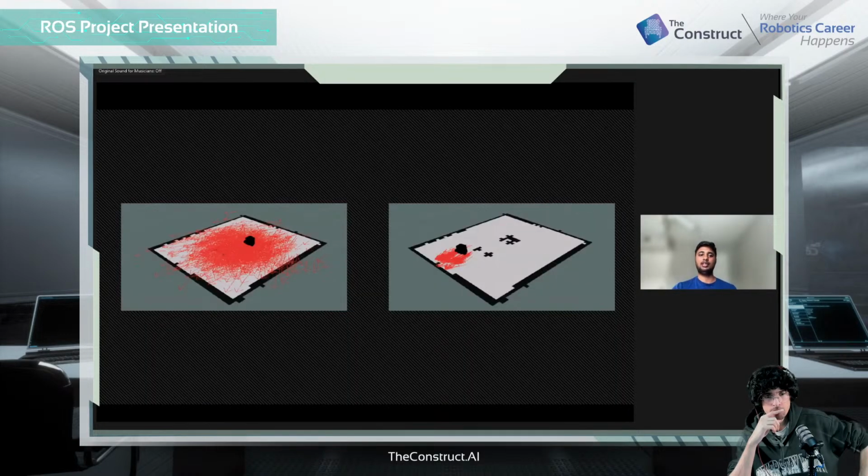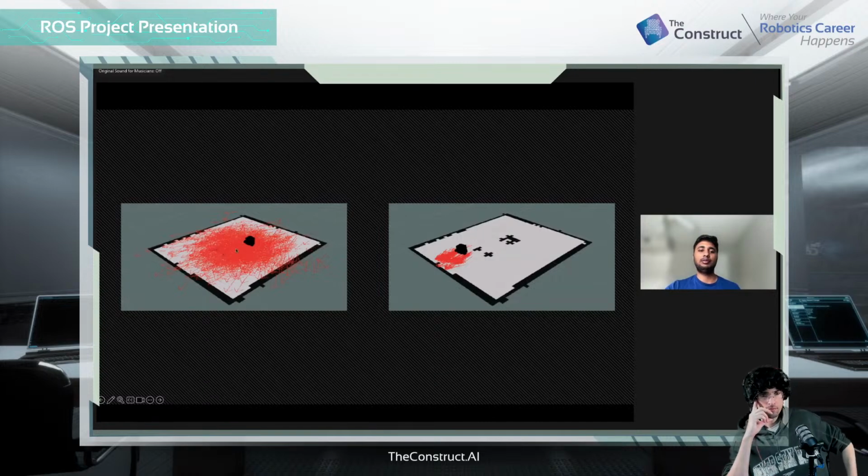This is basically the difference. When you just initialize the robot, the particles are uniformly distributed all over the place because the sensors have not yet gained information and perception of the environment. Once you move the robot around, these particles automatically cluster together to form higher accuracy estimates, which helps the robot to localize and move around with accurate positions.